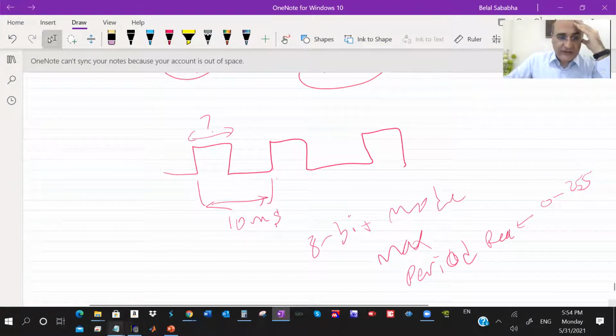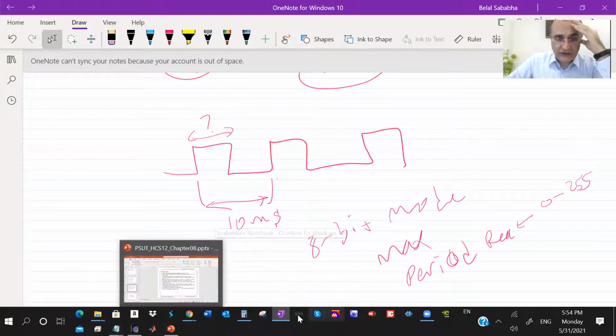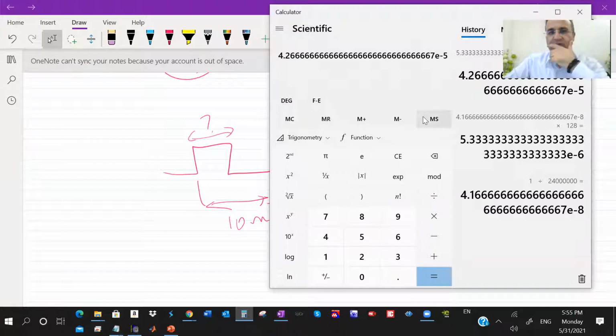So what I did here, I have a count. Where's my calculator? Here. Every count will take 42.6 microseconds. Let me save it. And I want 10 milliseconds.